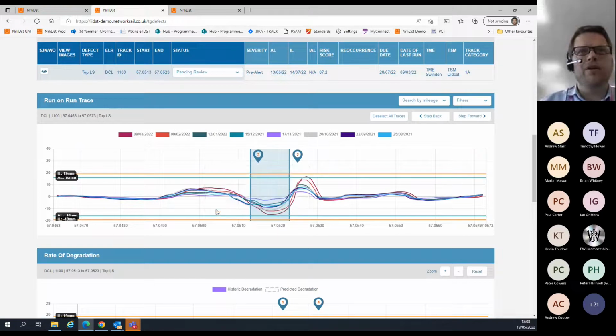Okay, so there's a couple of things we do. First of all, we run an alignment algorithm. It's cross correlation to line up. It takes a signal from the top right trace, and it will match it based on that signal. So it shifts the measured location left and right slightly, squishes and squeezes it to get the traces to line up. So that's the first thing it does.